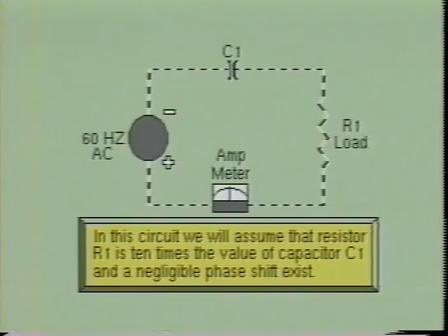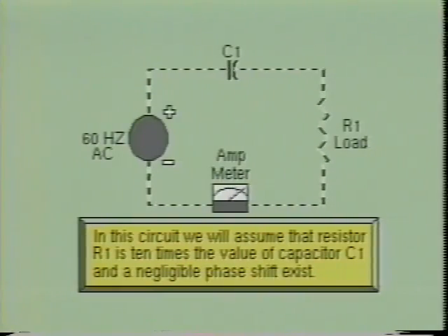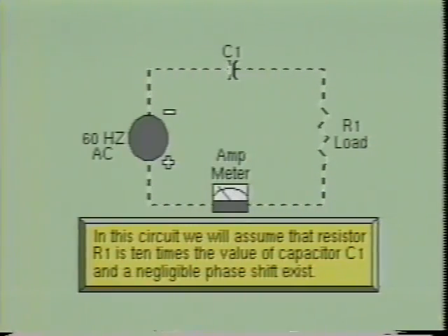As the AC sine wave continues to alternate first in one direction and then in the other, the capacitor will continually charge and discharge through the load of the circuit. As you have seen, the load resistor sees a current flow first in one direction, then the other. As far as the load resistor is concerned, the alternating current is flowing through the capacitor, even though no electrons actually pass through the dielectric.